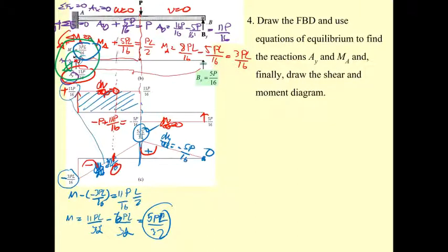So what we have from this is the elastic curve. Our curve is going to be like this. This is fixed. This is concave downward, and the other portion is concave upward. So this is going to be the elastic curve of this beam.